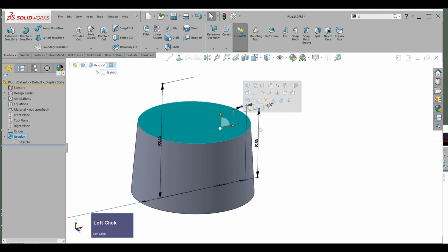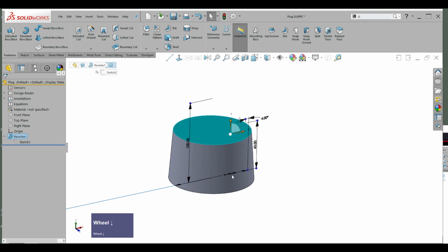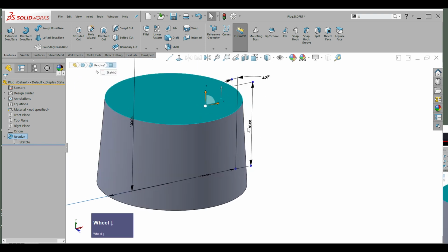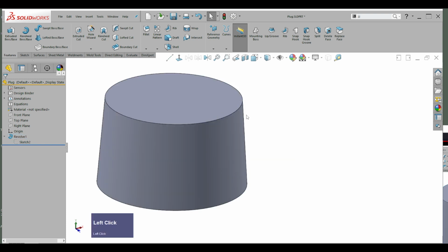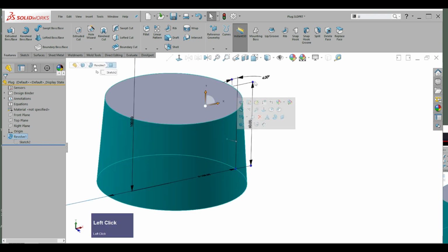So it's incredibly powerful when you put the dimensions in. This program becomes incredibly powerful because you can alter it on the fly, and that's what parametricity is. It's that once you have the dimensions, you can drive the shape from just using the dimensions. You don't have to do anything else. You don't have to go into the sketch and alter the sketch. You can just use these points and do that.